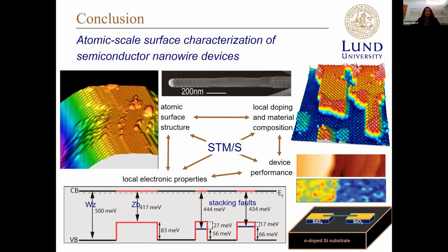Yeah, sure. I'm sorry if that did not get clear in the presentation. Well, SEM is the standard technique, scanning electron microscopy. It's a standard technique which is in many labs, where you have an electron beam, which from far away from the sample is focused on the sample and scanned across it, and you look at the backscattered electrons and get an image from the secondary electrons, which can nicely show topography, but not much more than topography. I mean, there are other methods available, yes.